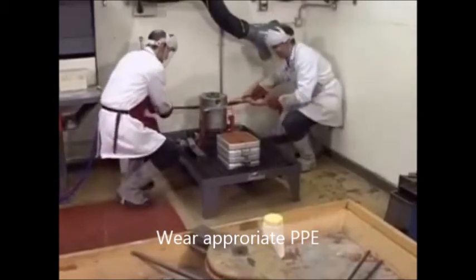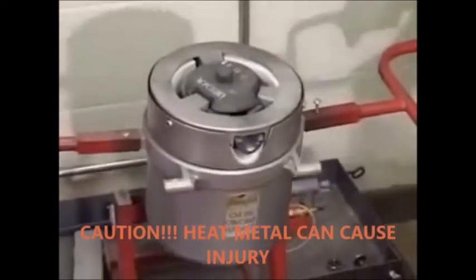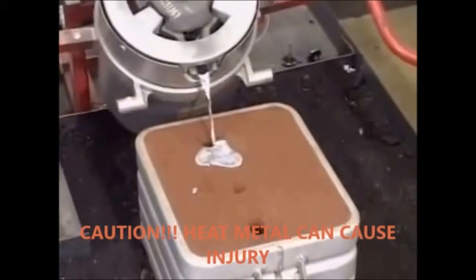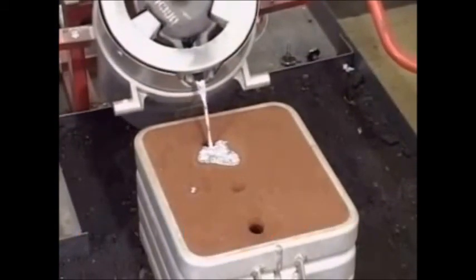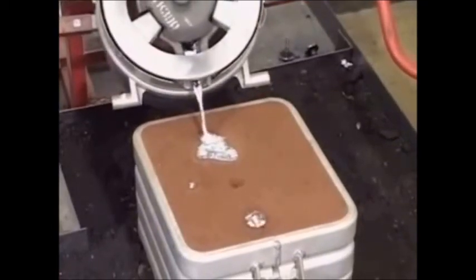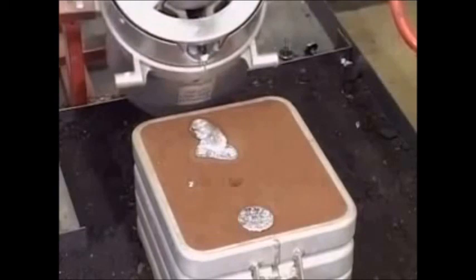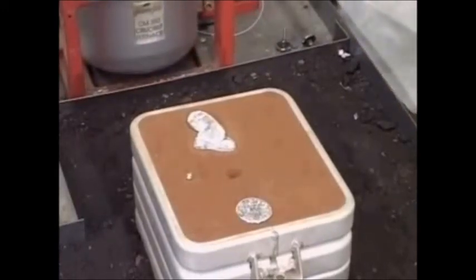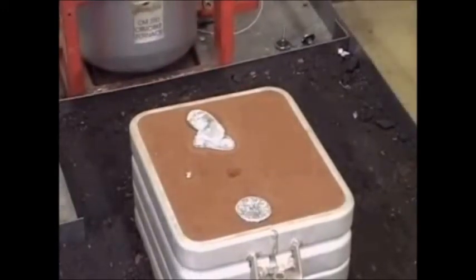Remember that molten metal can cause horrific injury. The pouring operation should be carried out in a single smooth operation. This will prevent voids forming. Tilt the crucible so the molten metal flows into the pourer. When the void is filled, aluminium will appear in the riser. The mould should be slightly overfilled to allow for shrinkage of the metal.